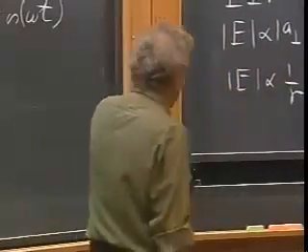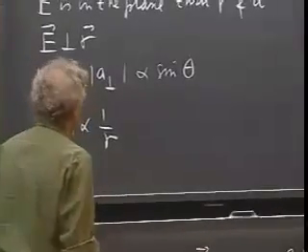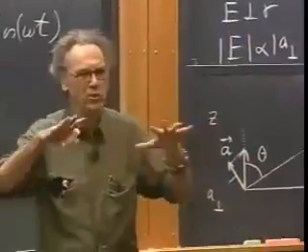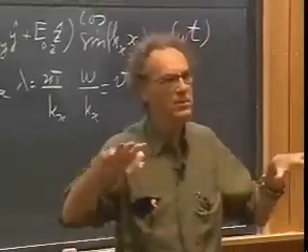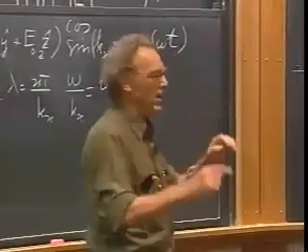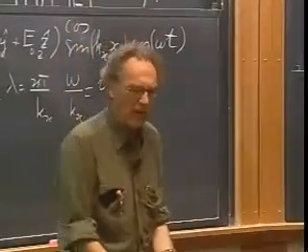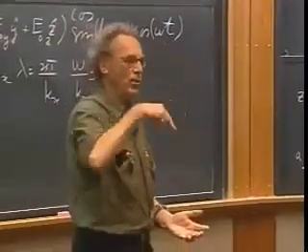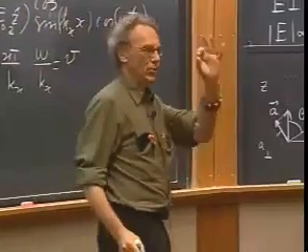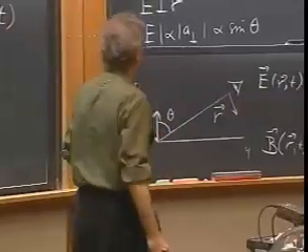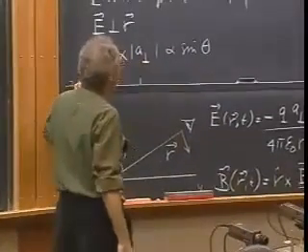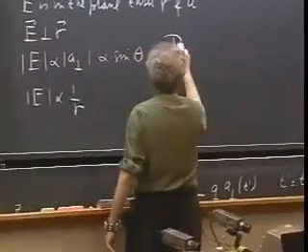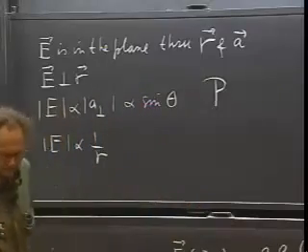If you're interested in the total power, so you're not interested really in the fact that the Poynting vector is a strong function of theta, namely sine square theta, but if you integrate the Poynting vector over one sphere that you choose, and you take the local Poynting vectors and multiply that by the local areas, which becomes an integral, then you can actually come up with a power. This is now in joules per second.